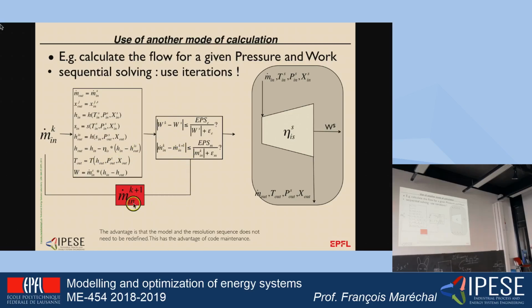So what I'm going to do here now is calculate a new value for the flow and make an assumption about the specification of the flow at the inlet, and then I will converge until I'm satisfied with the specification which will be tested here. Okay? In this case, the system will be linear. So if I'm applying the simple methods that I know to solve nonlinear equations, I will calculate the derivative. And after one step, I will have obtained the flow in the system.